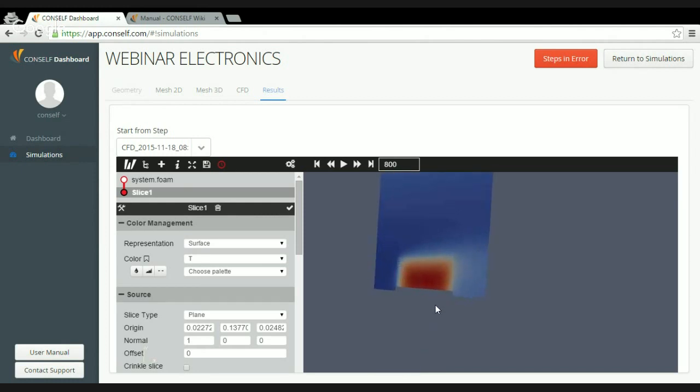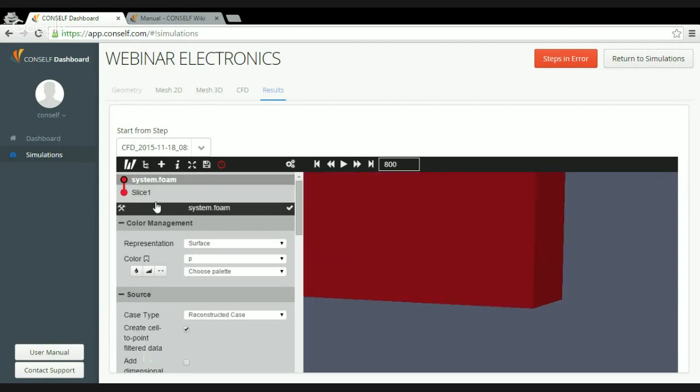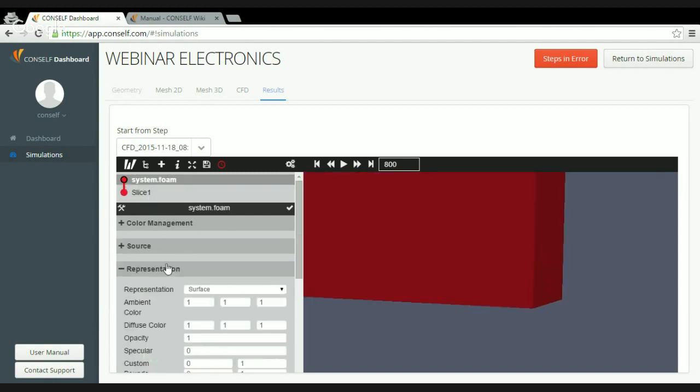By moving the slice, I can zoom in to the zone inside, and I can actually see that this red zone highlights a high temperature zone, which is actually convected in this white zone. This is the convection of the flow, the heat extraction from the CPU. In order to locate this slice inside of the boundary, inside of the volume flow, I simply define an opacity to be lower than 1.